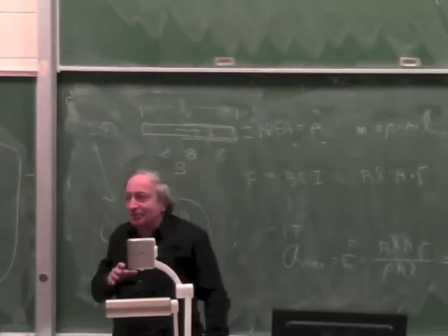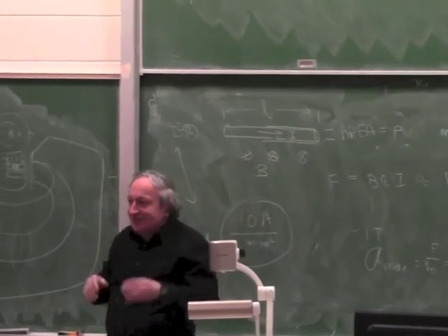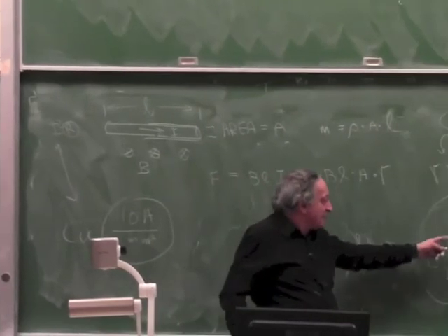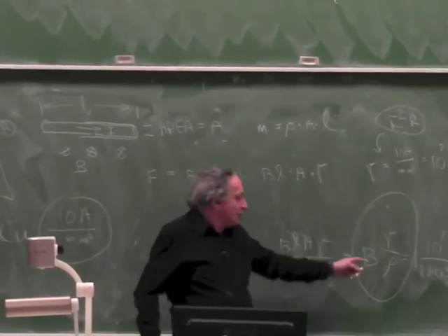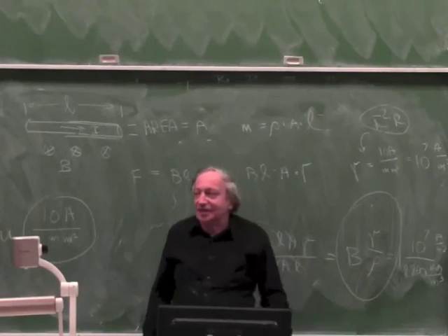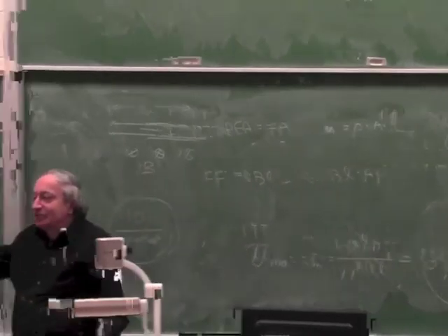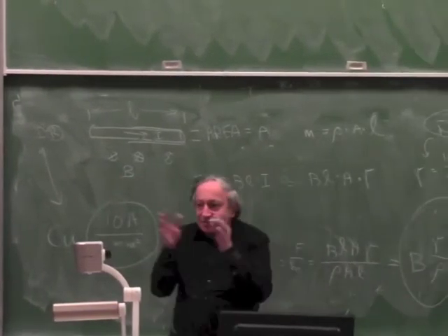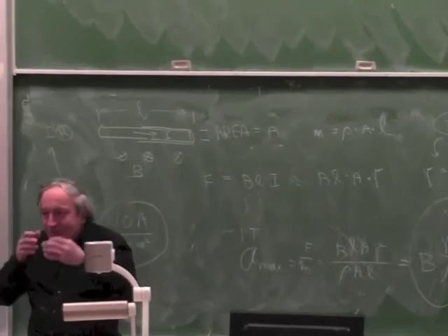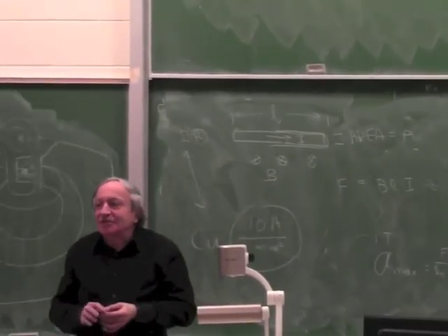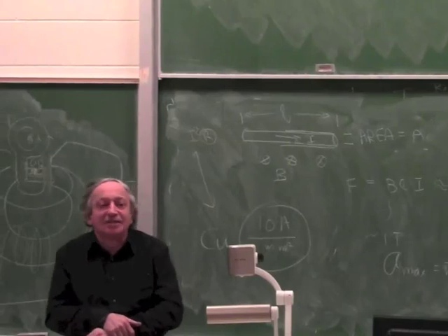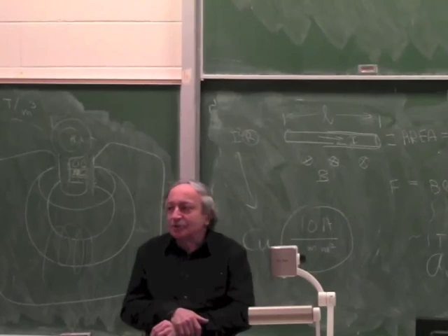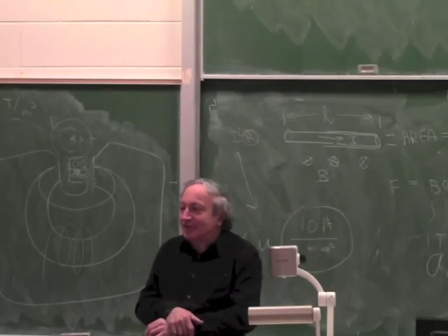I won't take you through the whole optimization, but you can envision it, right? Because if B goes down a little bit, it cancels some of the gain. Because the ratio of current density to physical density, let's say, is 1.6 or 2, but you have to discount another 10% because B will drop a little bit, because you have to increase the gap. Anyway, you can go through this whole calculation. I won't bother you with it. So the bottom line, it's still at least 30% better. And because of that, the highest performance actuators are actually made of aluminum wire.